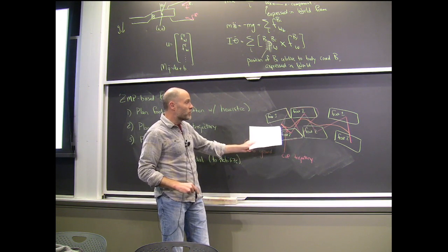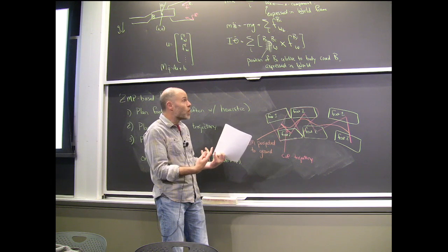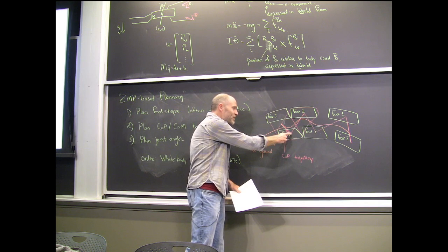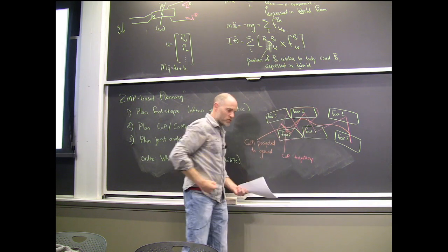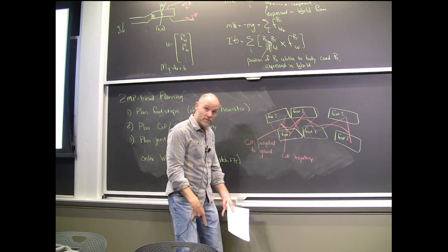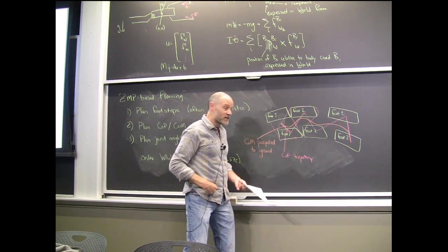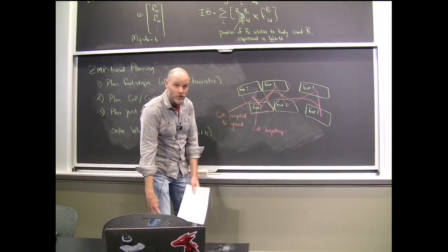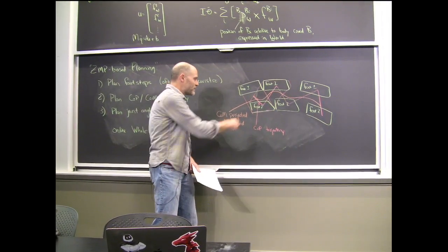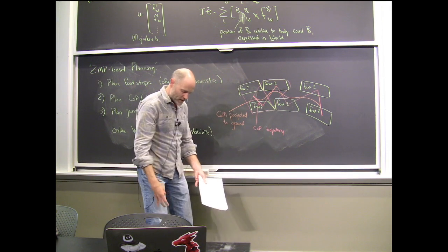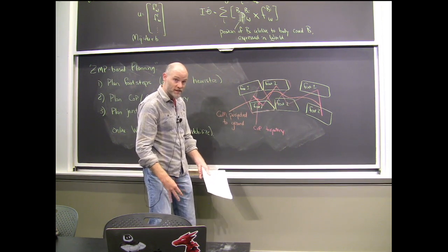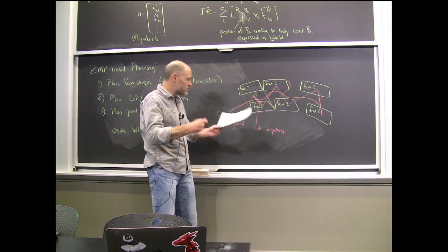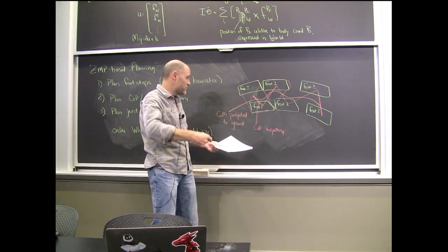So the only thing that matters is knowing that I can get forces. So if my ZMP is here, which I can guarantee by executing a center of mass trajectory, if I just know the positions of my feet and the positions or accelerations of my center of mass, I can figure out where my center of pressure is, or I can measure it directly, okay? If I have a desired ZMP trajectory and I'm not in the right place, I can apply slightly different torques to stabilize it, or I can move my center of mass slightly differently. You can choose whether you want to stabilize the ZMP or stabilize the center of mass.